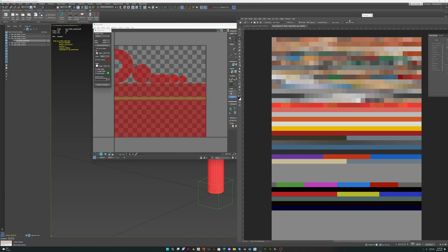Okay, so this gas bottle, if for instance I'm saying, okay, I know these gas bottles are red, but to stop people noticing the copy and paste of the same model, I could apply a palette to this and assign, say, this line here, which has many different shades of red. So what that would mean is every instance within the placed model would have a different color. So it doesn't look like it's copy and paste.